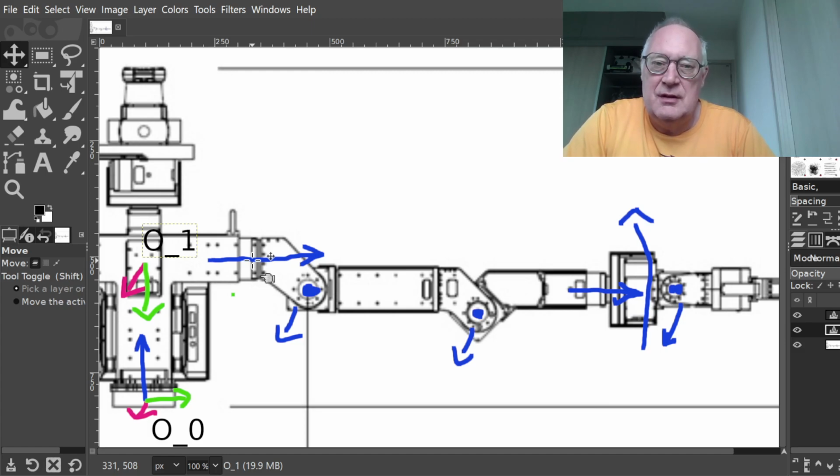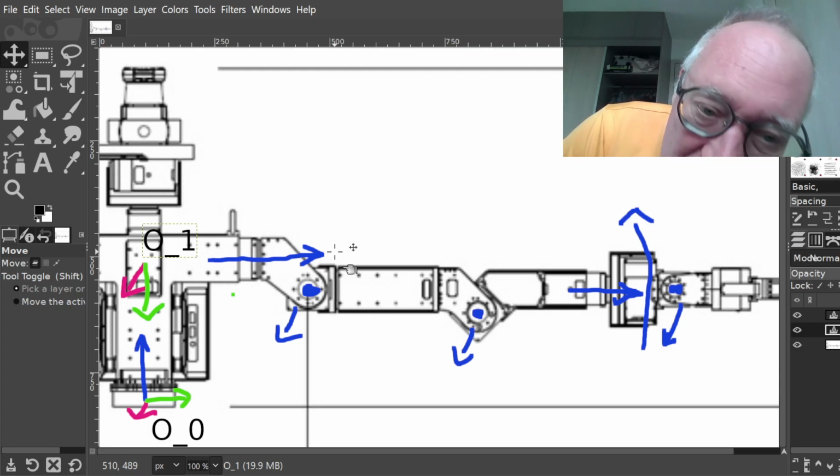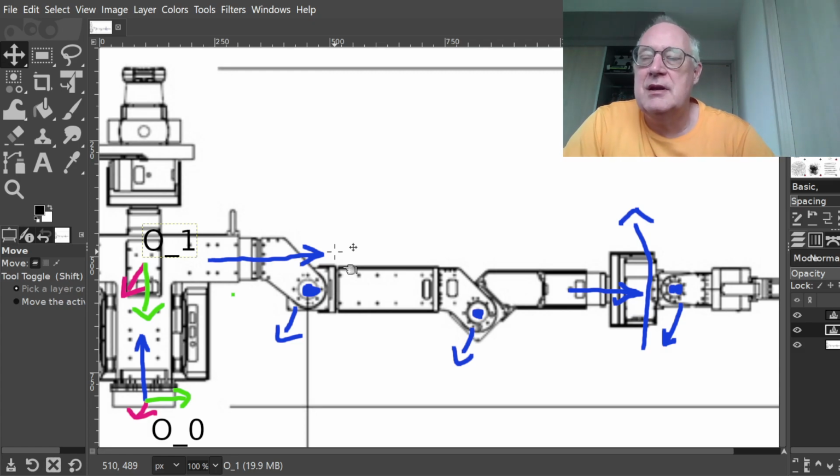Even if that takes a little bit more computation or is not following the Denavit Hartenberg convention, I like it better that way. But yes, many people use Denavit Hartenberg very successfully. It certainly works. And if you're dealing in industrial settings, for example, then the industrial robots all use the DH convention because they usually have simpler kinematics than humanoid robots.